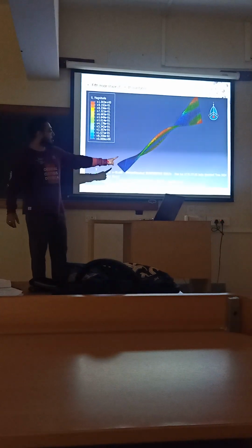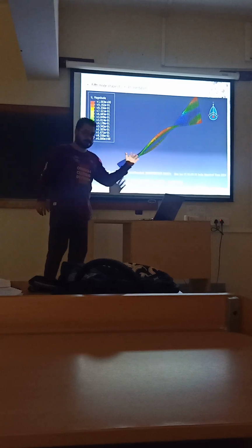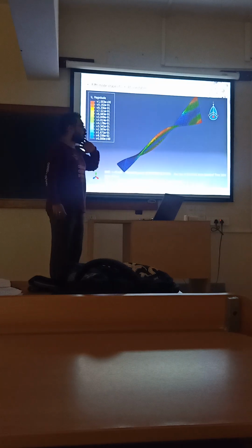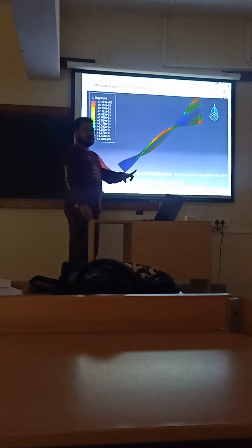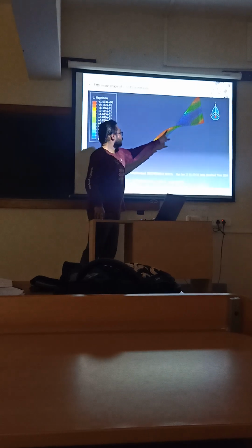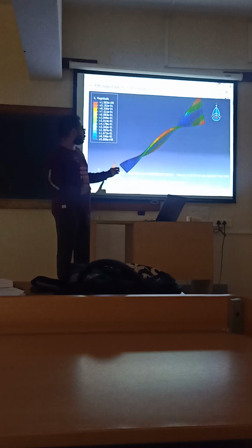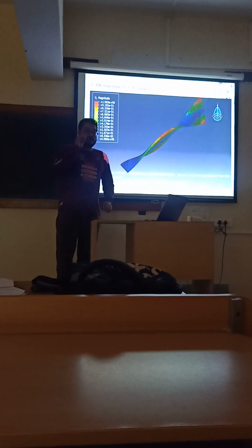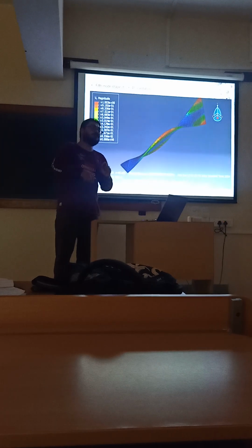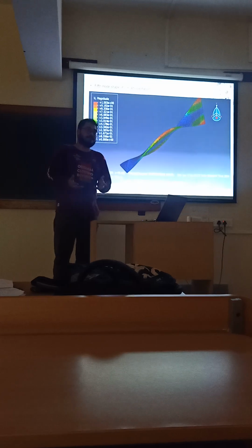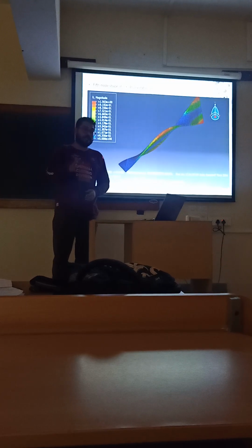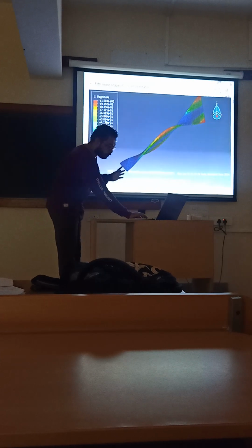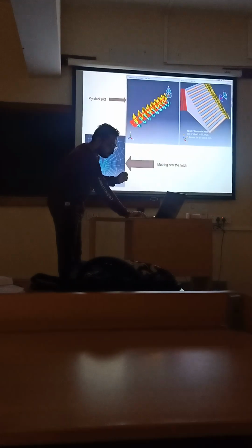This is the fifth mode. This is the only twisting mode among the first 5 mode shapes. Look at the complexity of this mode shape. Any crack or any defect situated here or here will have a devastating effect on this mode shape, on this structure. So any change in the natural frequency due to any crack or any defect, any impurity, will be more prominent in the higher modes due to the complexity of the modes. That's why there was a higher focus on the higher